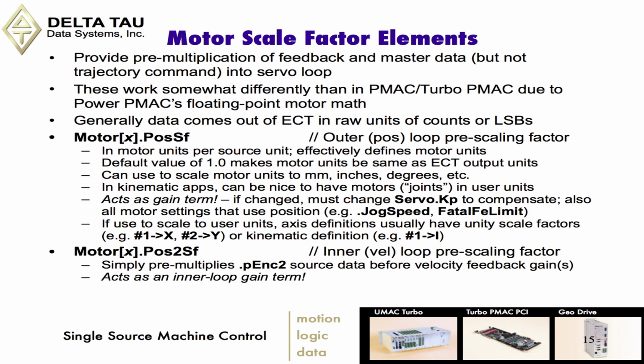There's a few motor scale factor elements. This provides pre-multiplication of the feedback and the master data, but of course not the commanded trajectory, because you don't want that to be interfered with, otherwise your path through space gets messed up.